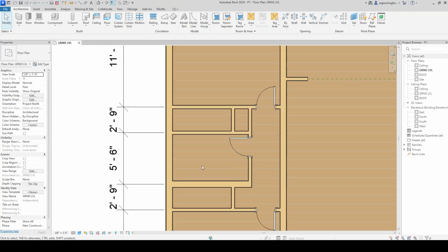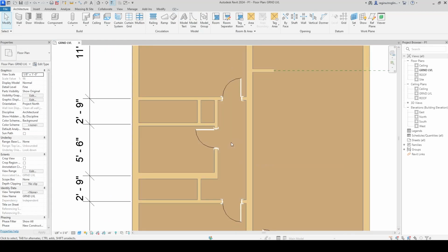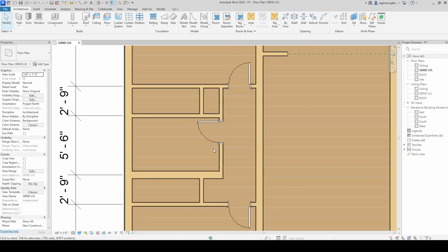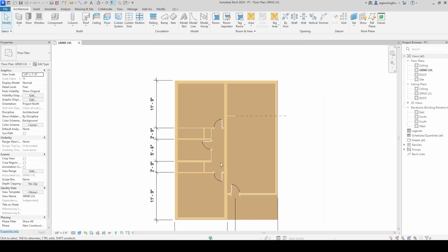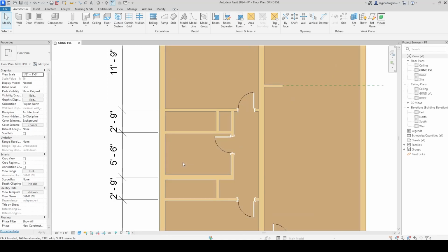I like to do that because in case, let's say this building were to be built, there is enough space now between the frame and the next section of drywall at the corner to both paint in there, but if the frame is slightly larger than I anticipated when it was ordered, there is a little bit of room for error. So once those are in, we're going to do the closet door next.